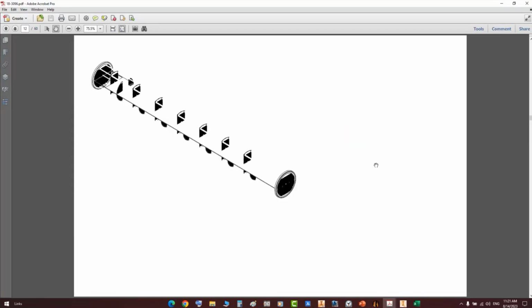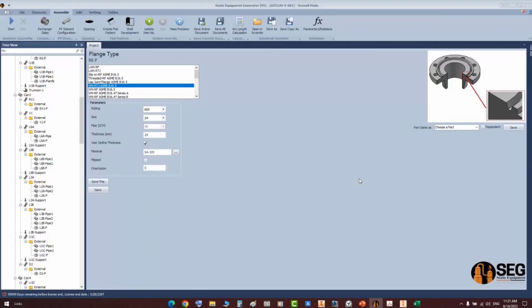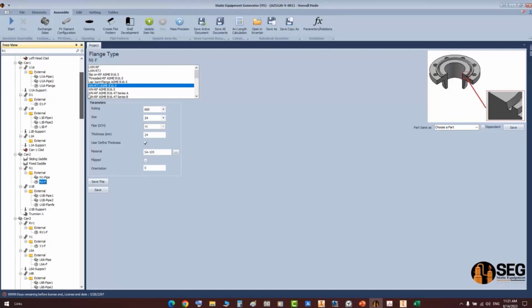Okay. But the bill of material part is still not clear. It should have been added in that bill of material section of that nozzle, but it has gone to the upside, no? Doesn't matter, Zaid, because the part number will be defined, right? So wherever it is, the part number is already defined. It will come as part number 4. Maybe it will not be in sequence. Yeah, because normally we categorize this, no? Nozzle N1, all the related parts, nozzle N2. Doesn't matter. But it will be listed there as well.